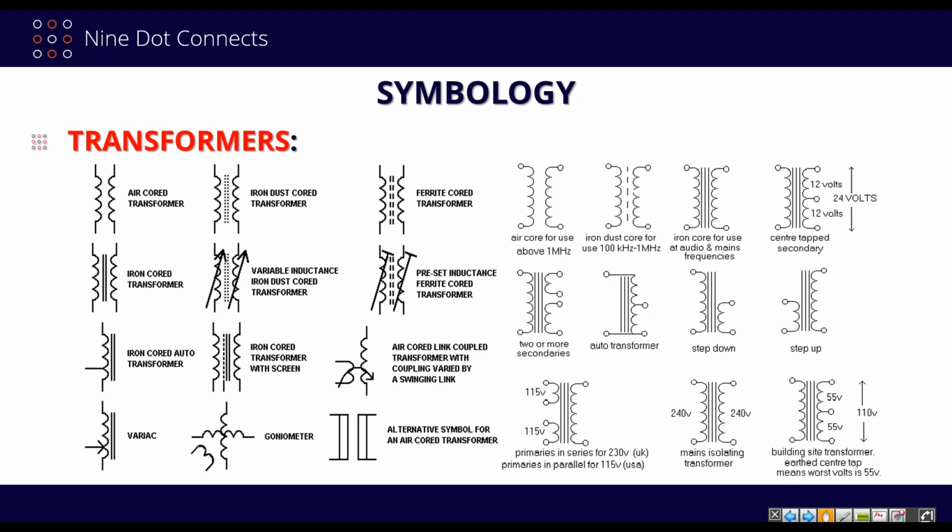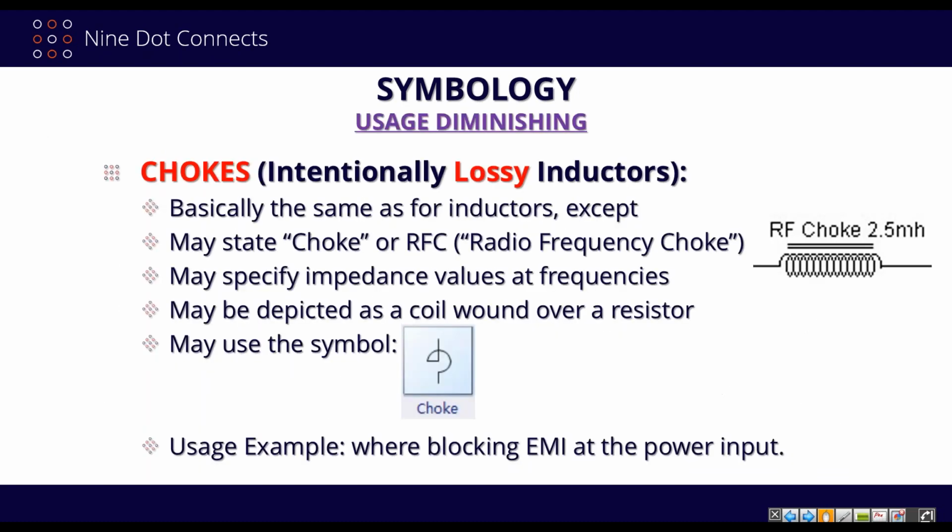All right. Chokes. Chokes are intentionally lossy inductors. Basically, for their symbols, they look very much like a regular inductor. However, they will oftentimes say choke or RFC, standing for radio frequency choke, near them. They may specify impedance values at frequencies and be indicated as a coil wound over a resistor, either a block resistor or a triangular shaped resistor. Sometimes they use the symbol shown there.